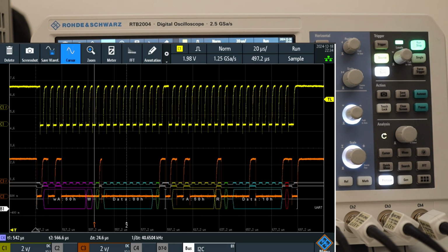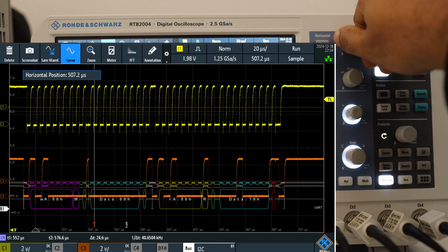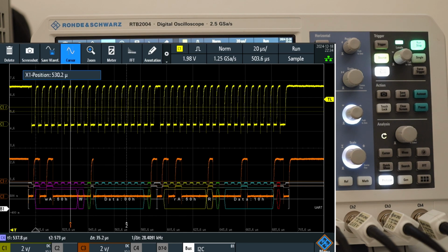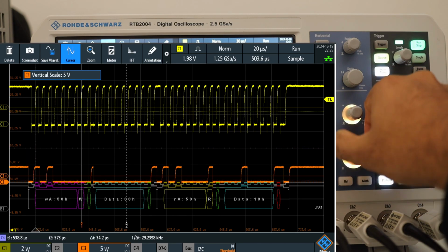So you can see this is the device address, right? On the cursor number 1, it says WA. It means it's a write cycle, and it says 50H, 50 hexadecimal, write, and green means acknowledge came. So both try to write something to the I2C device address number 50 and acknowledgement came. And if you follow closely, I'll maybe move the channel away from it and make it smaller.